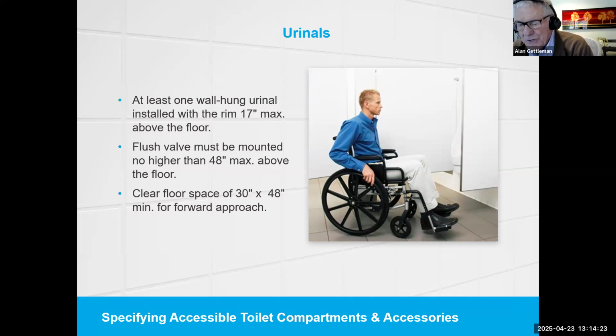It's 1.5 inches, and that's why we now recommend putting those accessories under the grab bar. Don't use the combination units that go behind the grab bar. There are combination units that Bobrick offers that are horizontal combination units for use under grab bars, not vertical combination units that go behind grab bars.